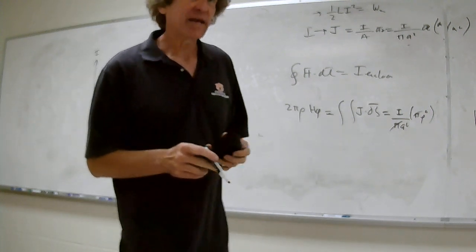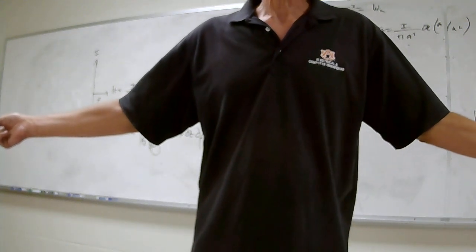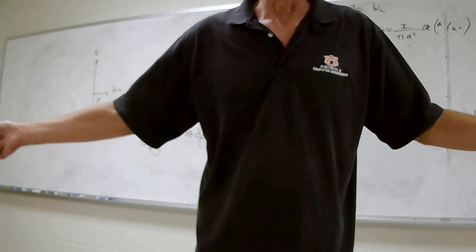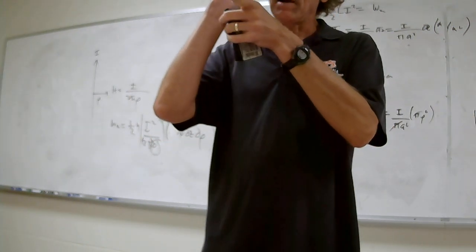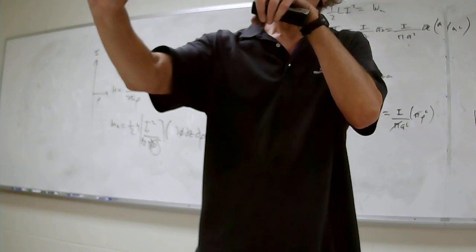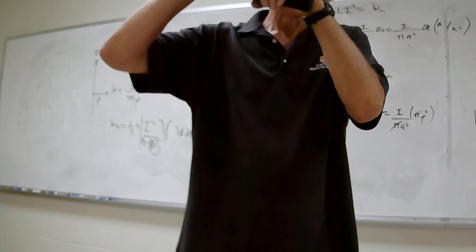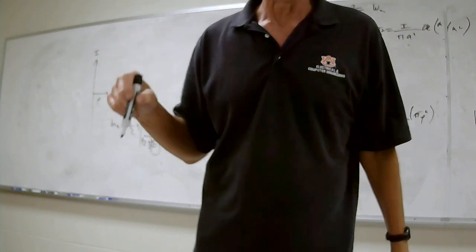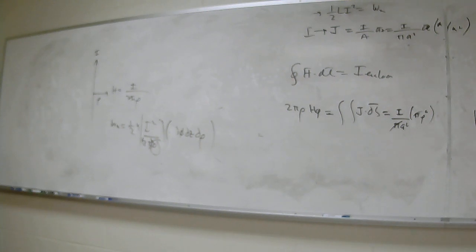But y'all follow me, you can't assume an infinite wire, because if you do, the energy density per meter is going to be infinite, that means the inductance is infinite. Well, there aren't no such things as infinitely long wires. So it all depends on the closure of the path. And by the way, if you have something that's in the differential mode, current going down one way and back the other, the closer those two wires are to each other, the less the actual inductance per meter is, which is good if you want something to respond quickly. You want very low inductance. More coming up on this.